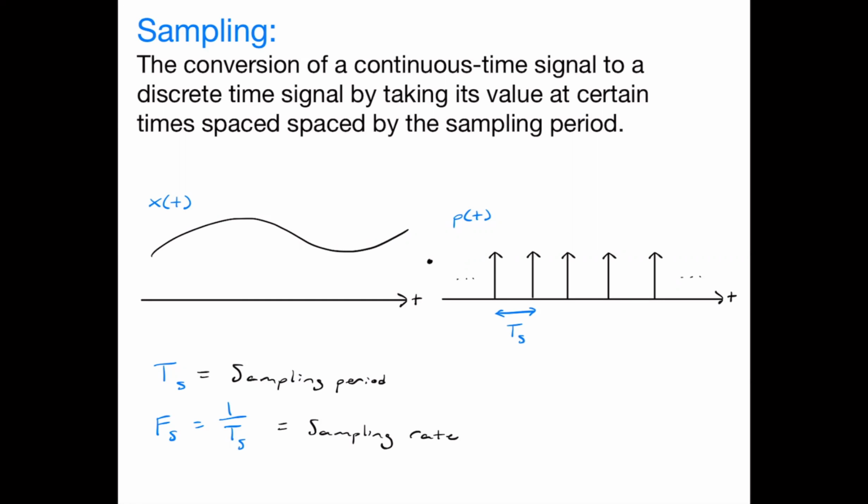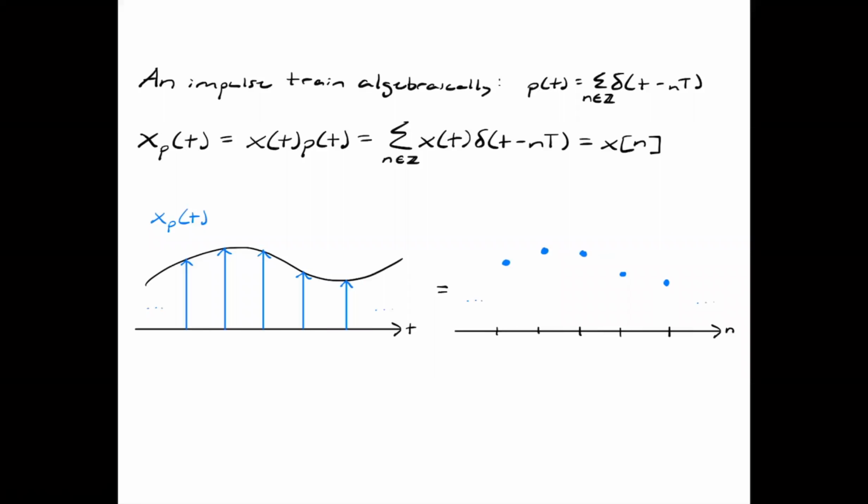This is done by multiplying the signal by an impulse train. As we know from the sifting property, each impulse will select a discrete value of x by scaling the impulse by the value of the function. This gives us discrete points which represent our signal in a computer, where we work with digital signals rather than analog ones.